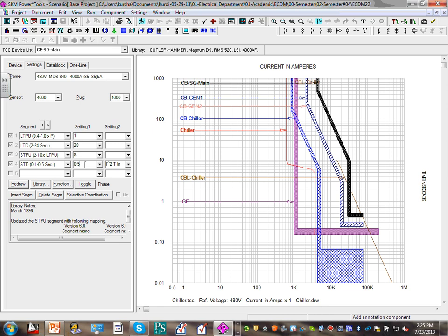Your equipment, if it's not rated for this, it will completely burn. Unless you have a zone selective interlocking switchgear, you would not be able to delay this one as much as I did here. Okay, so that's the reason why we did that when we disabled the instantaneous. That's when the code requires now to have that maintenance switch, where the maintenance switch will drop this leg down.